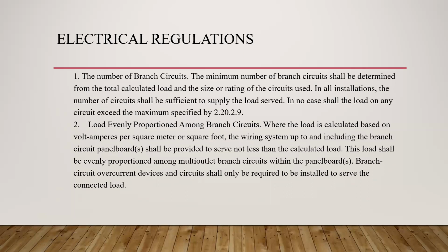In all installations, the number of circuits shall be sufficient to supply the load served. In no case shall the load on any circuit exceed the maximum specified by 2.20.2.9. So later, dun sa ating sample computations, mame-mention naman itong mga comments from these codes.